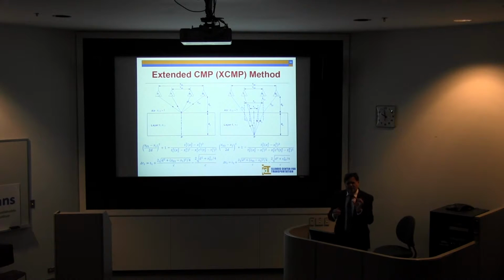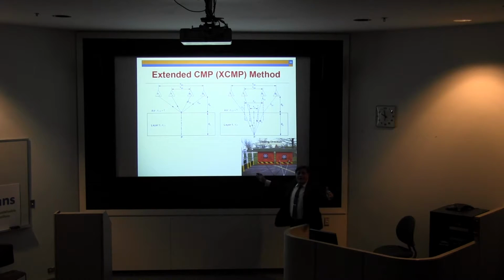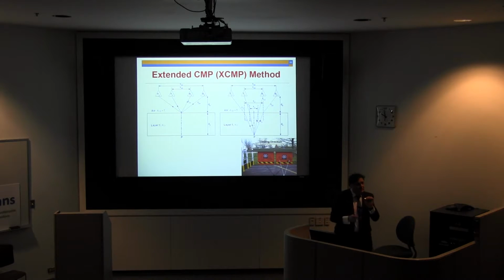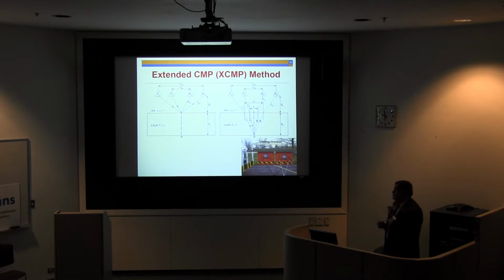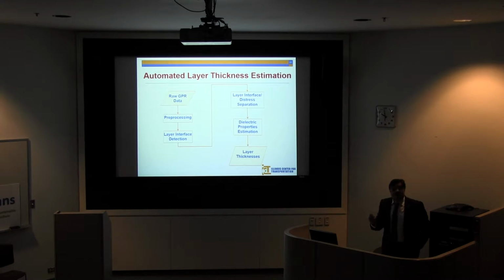There's one trick to this here. If I go back here, if I can make these two antennas far away, I will be able to have my measurements more accurate. If they are close, then the difference, we're talking about nanoseconds here. So we're talking about very, very small time, so a small error can make a good difference here. So the further you have them, the better it is. That's the only concern that we have, but we use this very, very successfully.